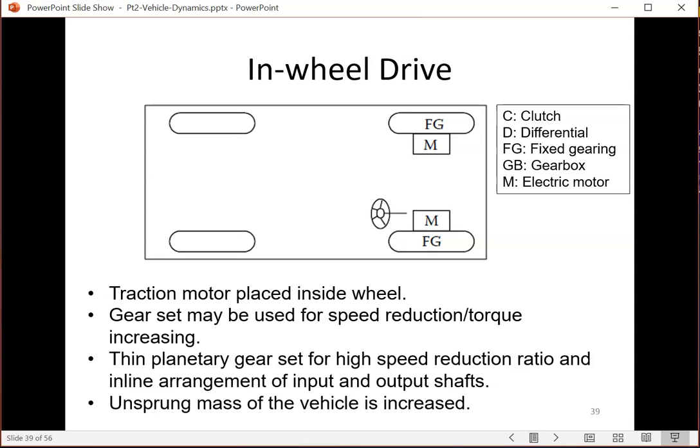because the tires tend to have a worse operating condition than when things are installed underneath of a chassis, because there's no suspension to isolate the vibrations. You have increased what we call unsprung mass. Okay, that's not very good for the dynamic behavior of a vehicle. Okay, and also you need some kind of special gear set as well.